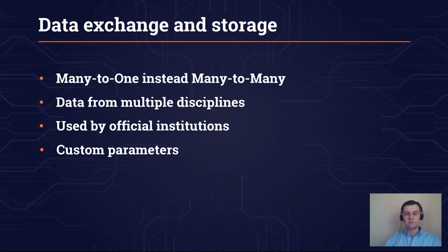And here IFC stands as an intermediate version or the single source of truth that allows to perform conversion in a many-to-one manner. IFC format aggregates data from multiple disciplines and also allows the usage of custom parameters. Due to all these advantages, it is used by many official institutions in many countries.